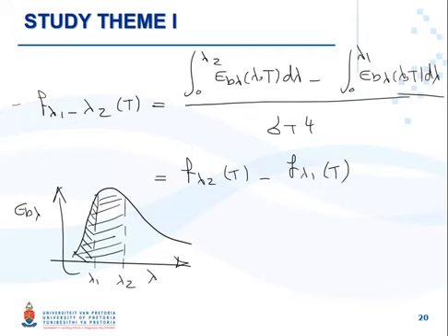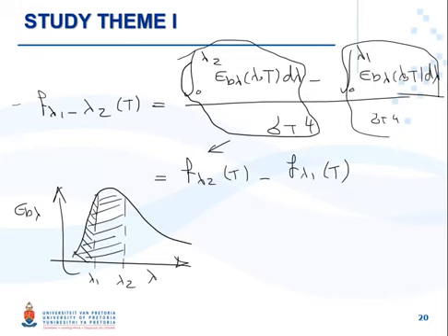We put it into the integration between 0 to lambda 2 for getting that area, and after that minus 0 to lambda 1. What we get is between lambda 1 and lambda 2. So this one basically is the definition of the blackbody radiation function. We put it here, again sigma T^4 can be here.